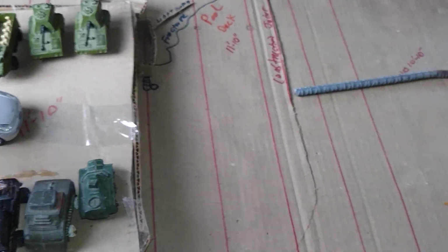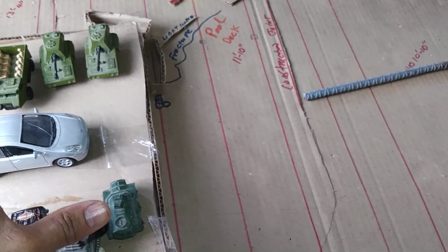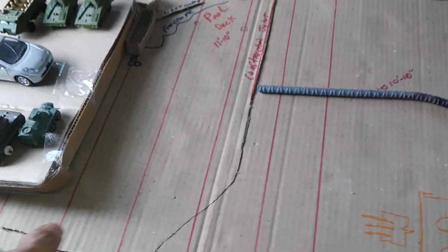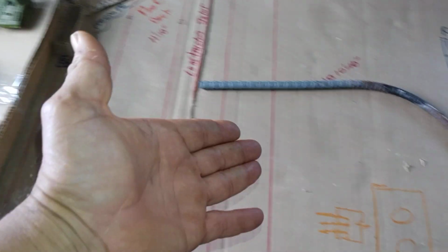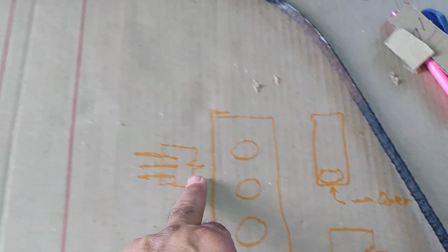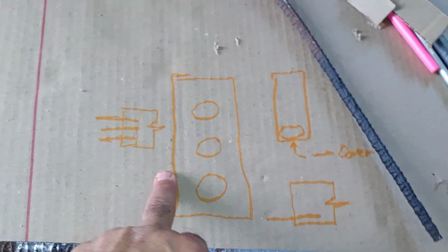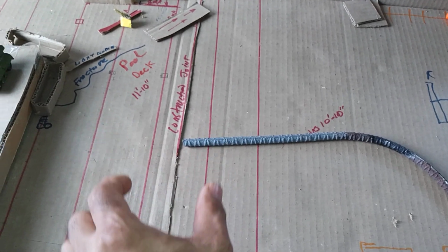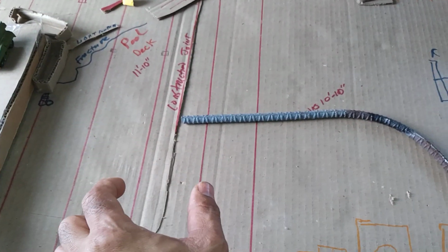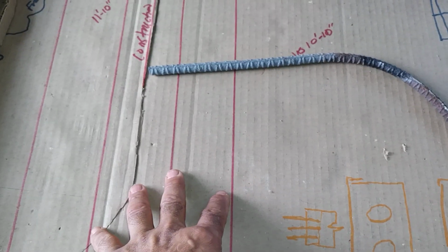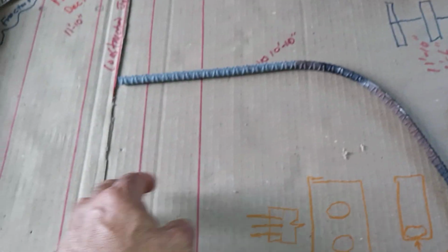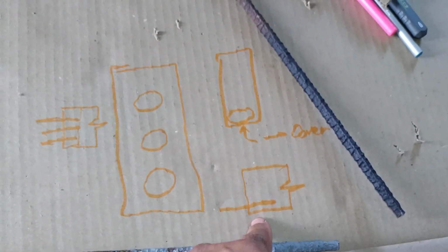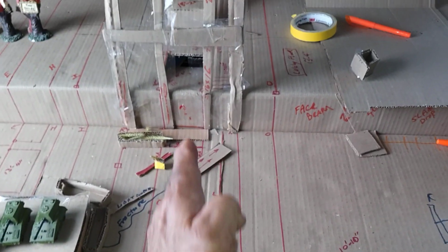So we got curb pressures, we got tires coming in, we got the shear action going on here because we don't have a beam. Okay. Then we got over here, if it didn't have the beam, would this have stopped it? Would this joint have stopped this collapse from going to that building? I would theorize yes, it would have a hell of a lot of deceleration that took place to stop the inertia of the collapse. It would have to start pulling at all this deck, possibly running it more that way if they had done this joint as such. But they put it down the bottom. That was an easy rip down, and a control joint allowed easy access to go over to here.